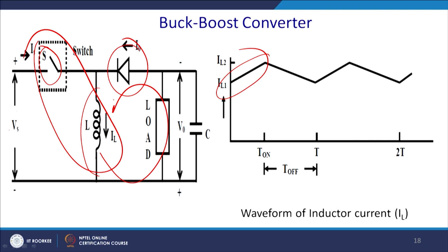You recall this, actually the switch off part of the buck, you will have the same topology, but here the inductor was placed here and the diode was placed in this position, just this has been interchanged. So, you just couple these two and ultimately you come out with this topology called buck boost.